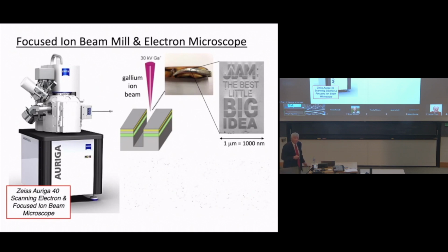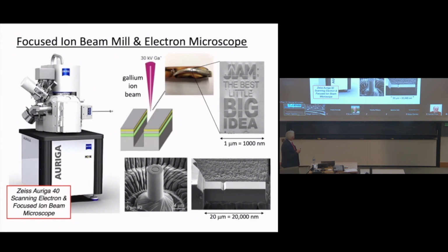And then from a more scientific standpoint, you can use these focused ion beams to carve out little pillars that can be used to do these small scale tests. Or you can also carve out small cantilever beams like this one right here. This is a notched cantilever beam that you can then bring a nano-indenter in and push down on the end of that thing right there. And you can then measure forces and displacements and look for when that cantilever breaks and do fracture mechanics kinds of studies to study crack extension at small scales.